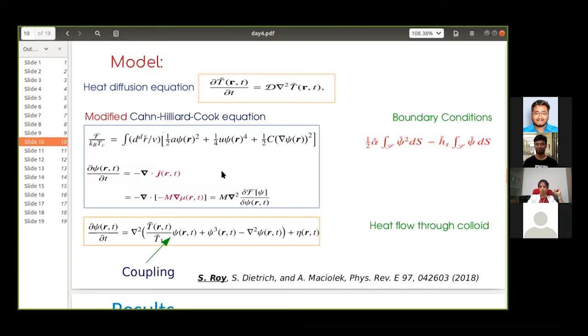Whereas in this type of system, as you see, we have a temperature gradient. So the temperature is once again a function of the space coordinate. It's a field. How am I going to take that into account? One way to do that is to replace this constant term A by the temperature field. Okay. And that's what is done here in this expression. You need to use some kind of tricks in order to replace the A by the temperature field.